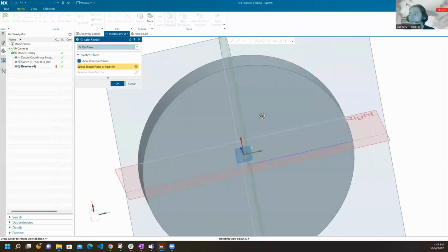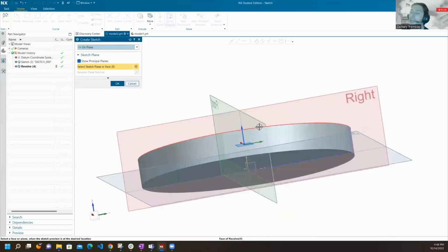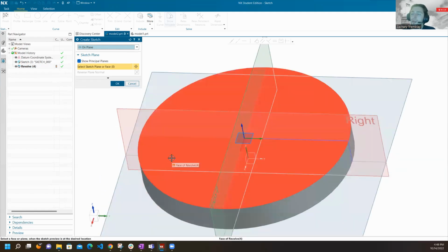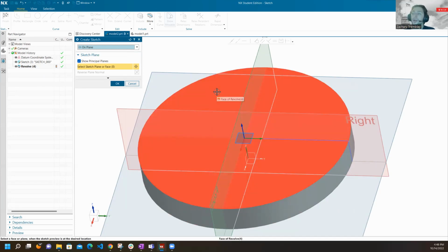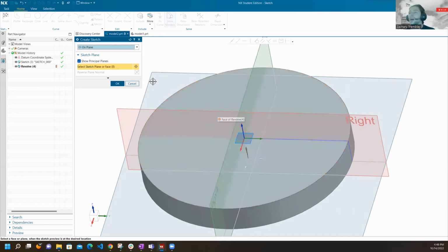this or plane of origin, as a side note, we are going to look at the good practices, and according to good practices, we should, as often as possible, try to avoid making a sketch on a face, because if the face later disappears when we make another shape, it's going to create a crash, and the whole CAD is going to need a lot of tune-up. So we oftentimes want to deal with datum planes. So this is what we're going to do.